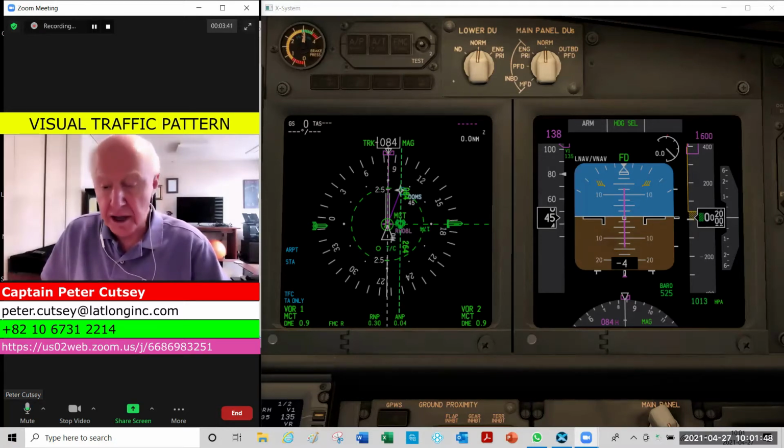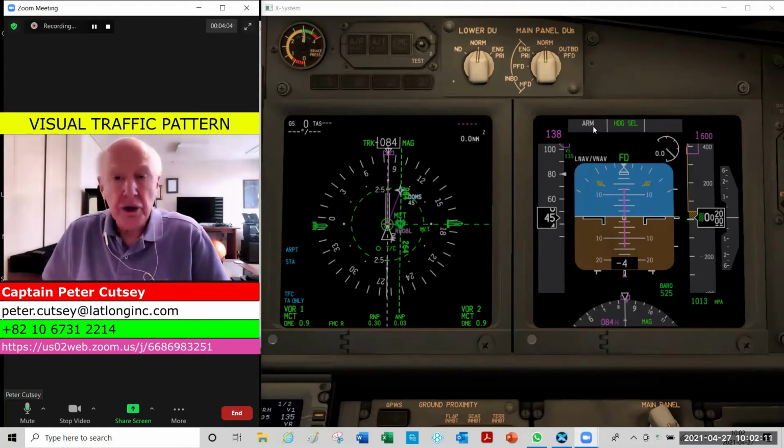We're on the flight deck now, and we have the nav display set up with the runway, on a 5 nautical mile scale, with a 90-degree abeam, the threshold of runway 08, and a 2.5 nautical mile circle. We'll talk about that in a second on the setup. We're going to use the auto throttles for the initial setting of takeoff thrust. We're going to use heading select to start with.